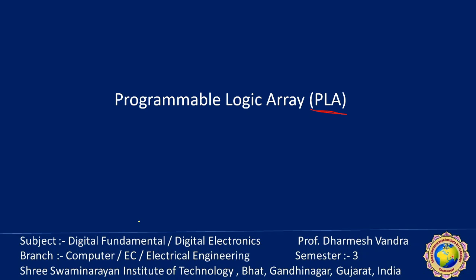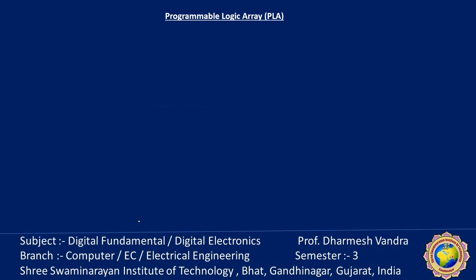So the same thing is also applicable in PLA. The PLA is a combinational circuit that may occasionally have a don't care condition. Sometimes in ROM the don't care cannot be considered. Here we specially consider the don't care condition. Remember that. When implemented with ROM, the don't care becomes an address input line that will never occur. So the main problem of ROM is that we cannot consider the don't care.